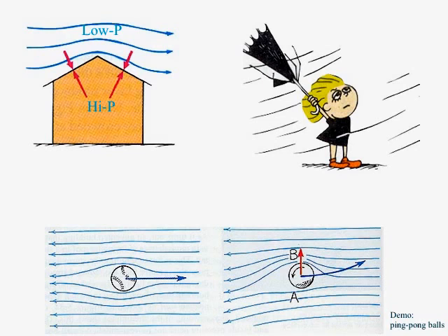That relative difference in velocity between spinning with versus spinning against creates a difference in airflow on either side of the ball. Where the air flows faster, where it's spinning against the motion, you have a difference in pressure. It could cause a lift and a pressure difference depending on which way the ball is spinning, which makes the ball take a curved path.